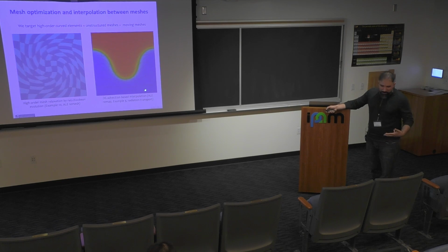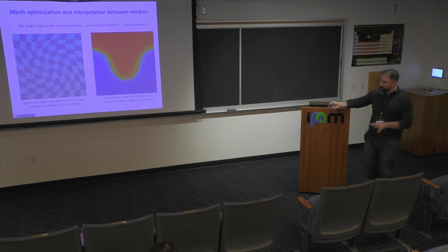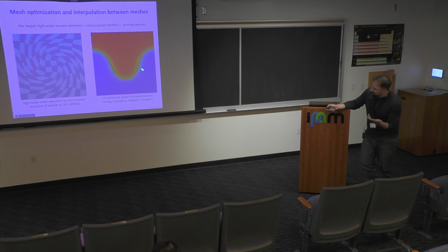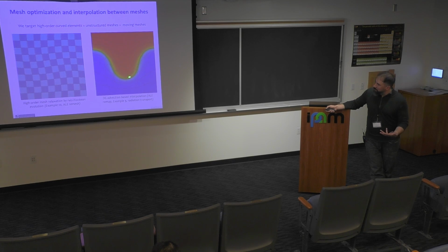You have the same function. The mesh flows through it. You want to preserve it. And this is a discontinuous function that's not aligned with the mesh. So you may not actually see it, but it's a higher order function that changes. And the fact that it's higher order allows us to capture this variation inside the element.